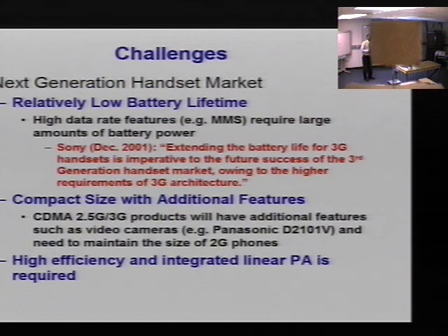So even in OFDM, the odds of me getting that high peak to average are such that I may have to sacrifice that high peak to average and try to meet my linearity over some length. It's an intractable problem to meet peak to average specifically for each of those.